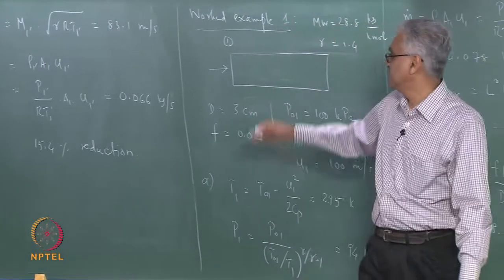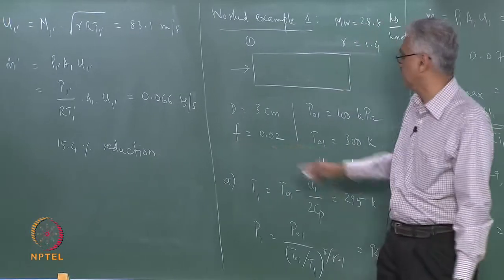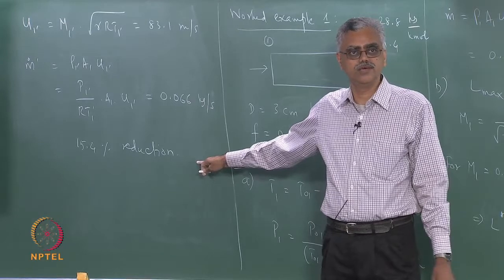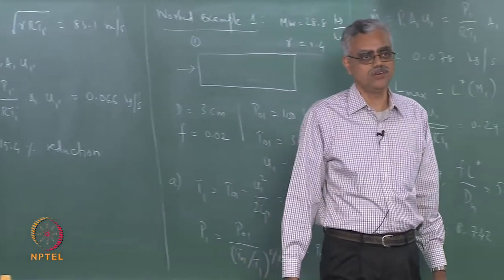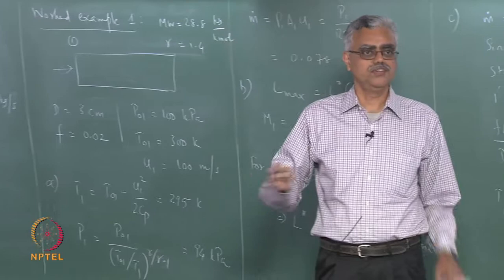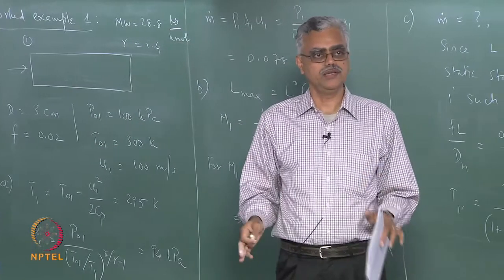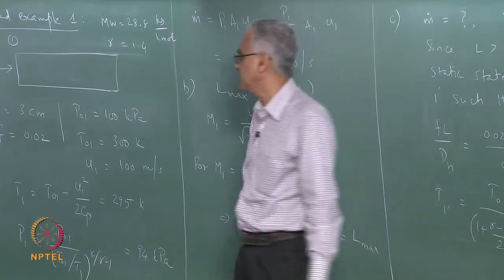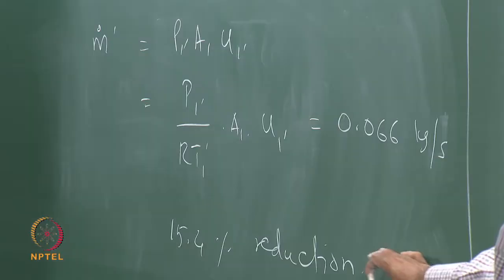Notice that at the exit state now, if you are using a 15 meter long pipe, the exit state Mach number is 1, whereas you might have designed the equipment for some other inlet Mach number, which is equipment connected to the end of the pipe. You may be expecting some Mach number and some mass flow rate, whereas the conditions are totally changed now.